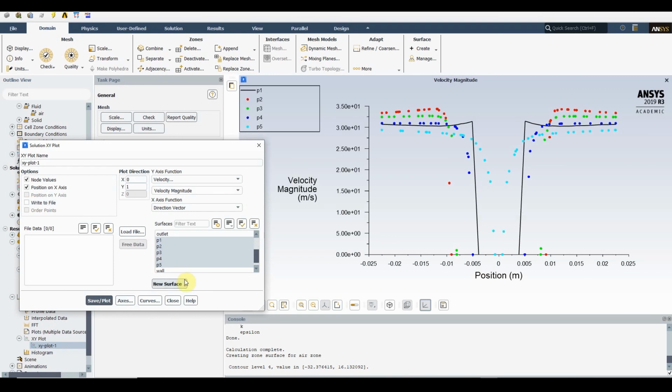Now, as I said, remember when you create all your post-processing images, your line rakes, it'll be only done for the 4 angles and for the best mesh and the best turbulence model. You don't need to do it for all of them, and you don't need to do it for all of your angles. So I know I kind of jumped the gun a little bit here to show you how to extract the data and the results for one of the questions, but again you would only do this for the best model. However, if you're not going to do a mesh dependency study and you're not going to do a turbulence dependency study, you can go straight away with whatever's best for you, just so that you can complete the assignment.